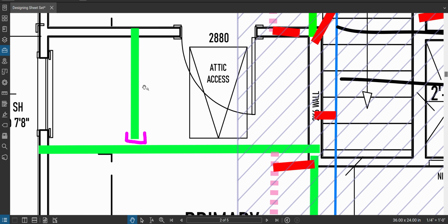Let's go into Forte. So first things first, drop beam. This is primary bedroom, front to back, rear. All right, code minimum, leave all these settings alone. Spans and supports. Let's go back to our drawing. And what I'm likely going to do here is continue to move quickly, because there's a lot of beams to do in here. We don't want this to take forever. It's about 3'9". Great, so I'll go back. I'll put in 3'9".